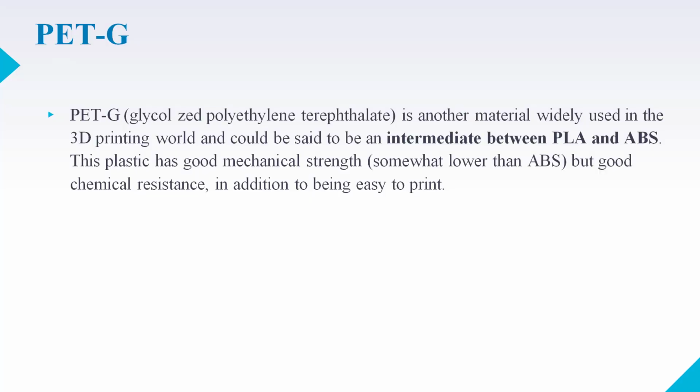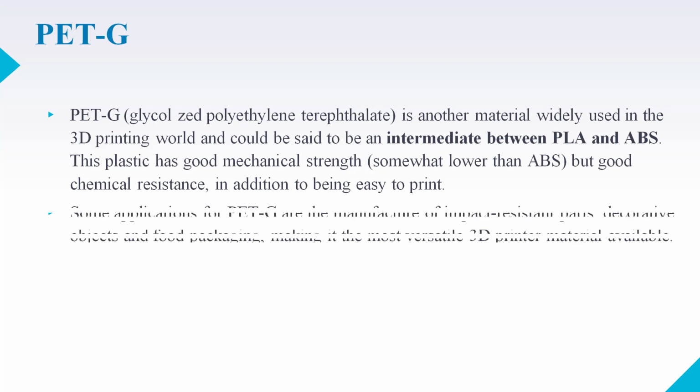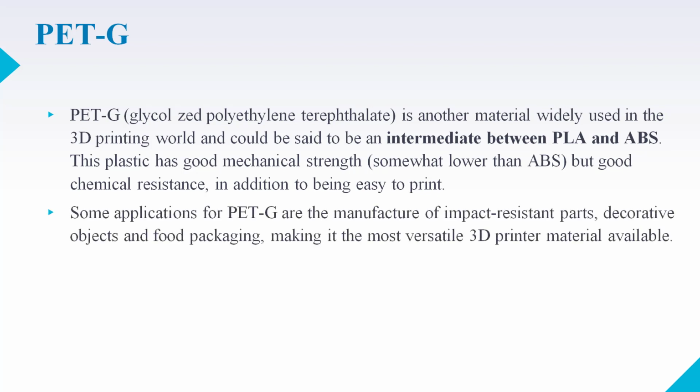So chemical resistance is high. When we talk about ABS, the chemical resistance is less, but PETG overcomes this drawback of ABS. It has a high chemical resistance and is also easy to print. Some applications for PETG are manufacturing of impact resistant parts.